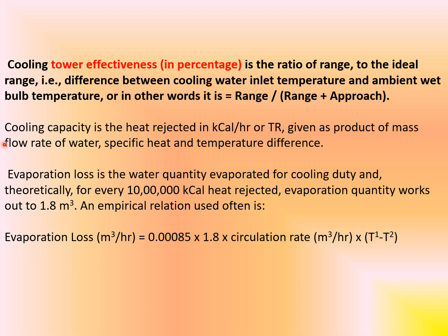Cooling capacity is the heat rejected in kilocalorie per hour or TR tons, given as the product of mass flow rate of water, specific heat and temperature difference.